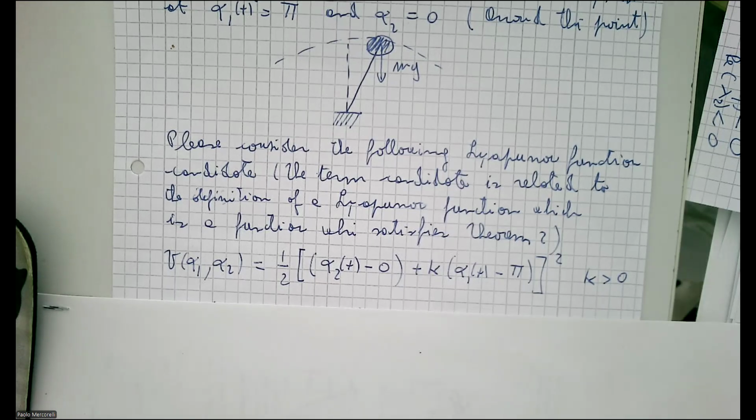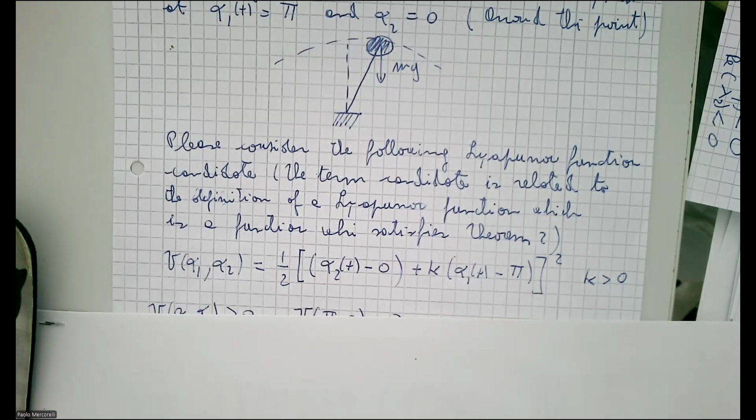This is the constructive one, because using this condition, better to say, it's not an equation, it's an inequality, we can build the control law which guarantees around the point the negativeness of the derivative. Do you remember, this guarantees that the system is passive, and asymptotically stable at the point, in this case the equilibrium point, but the same consideration can be done on a trajectory. What is the meaning of the trajectory? I'll show you in one second.